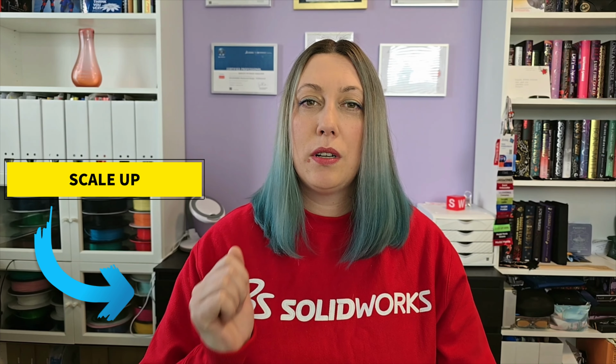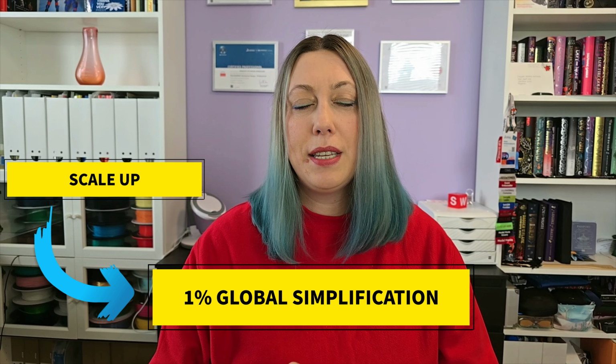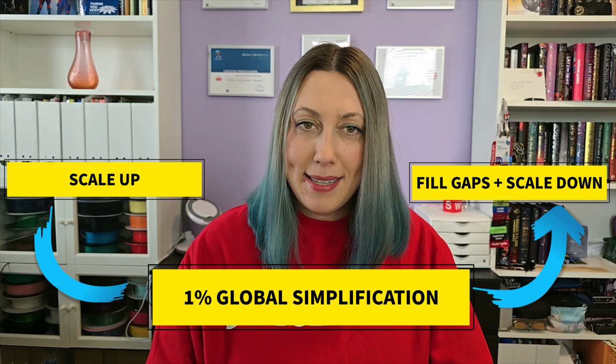So when you import a part and you receive the error message that it's smaller than 1 millimeter, or you're having trouble fixing the mesh, then it's better to scale it up to a bigger scale, run the mesh preparation wizard, reduce the facets with 1%, then repair the holes, and you can scale it back down to the way you want.